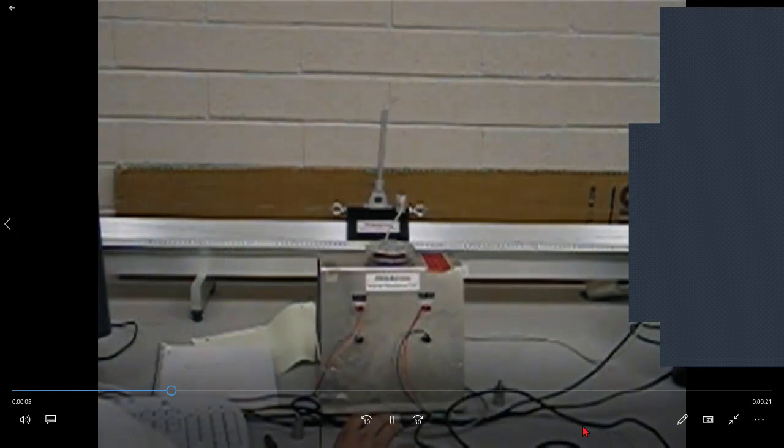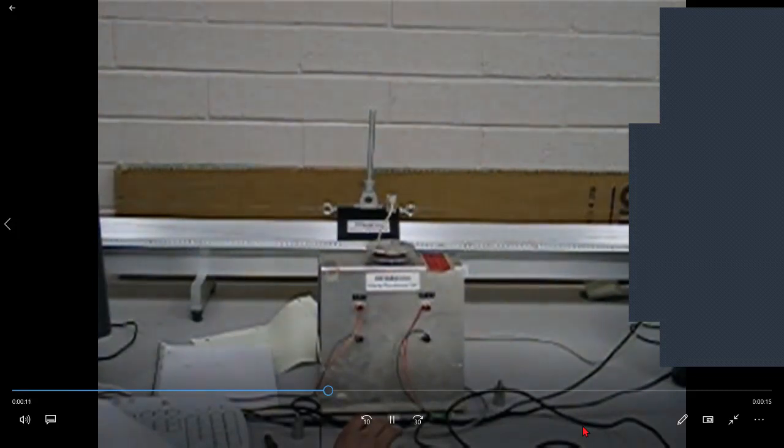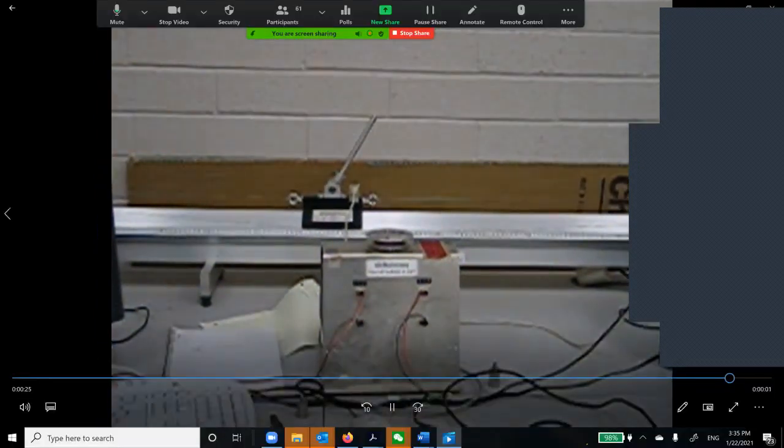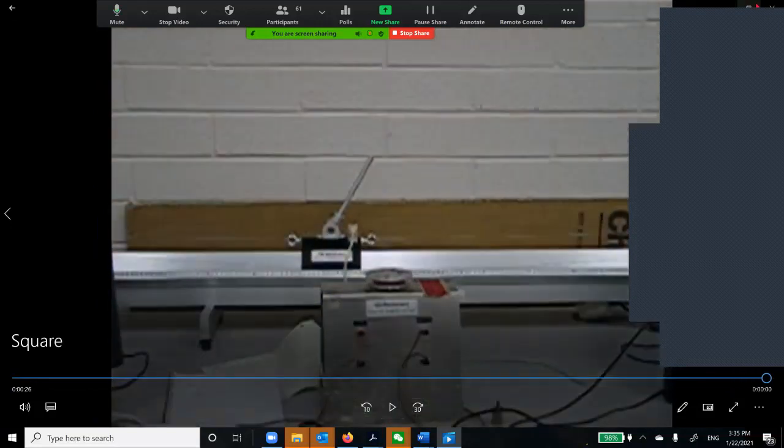So you assume that you can measure: there's an encoder in here, and there's also an encoder in here, like how much distance you traveled. And also I want this cart to stay here, or here, or here. So it's called a square wave. So you need some adjustment to make it upright. This is a typical mechatronics control example. It's actually very difficult to control. You need to use a lot of modern control ideas to make it work.